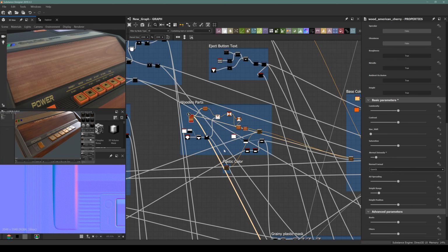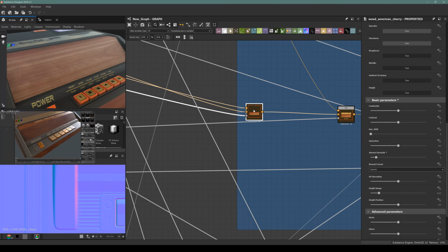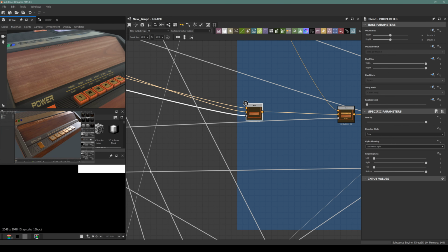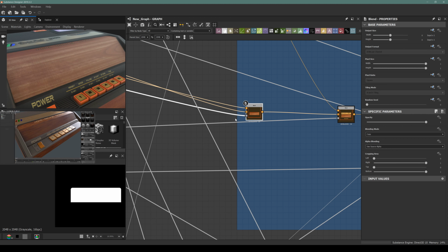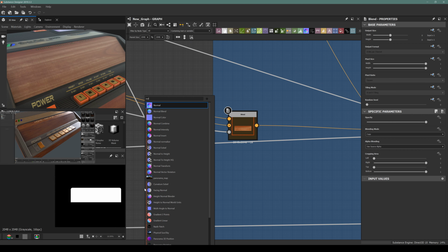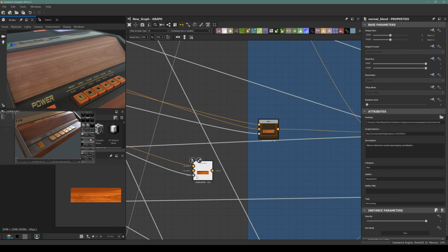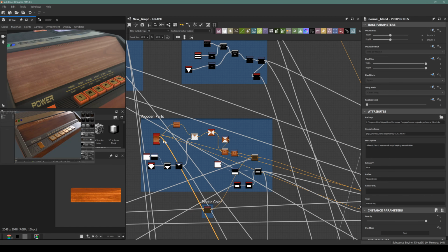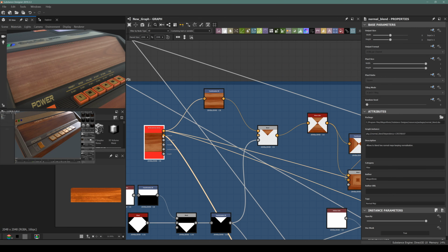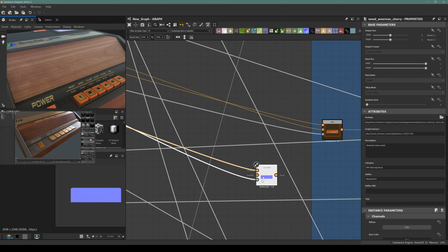All right. So we will be having another normal map detailing like this on this map, on this mask actually. So let's add another normal blend. I will use the base color for a starter, but my next step will be connecting the normal channel output of the material to this normal blend node I have.